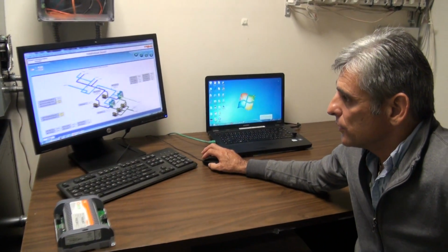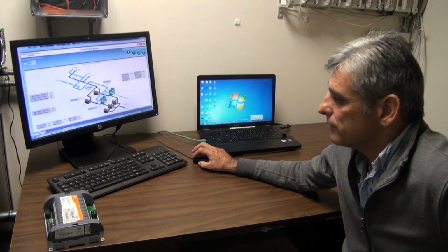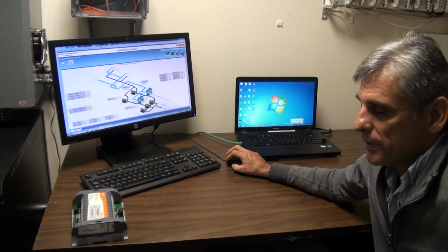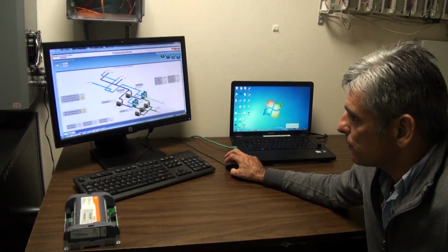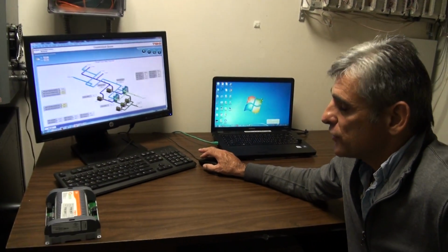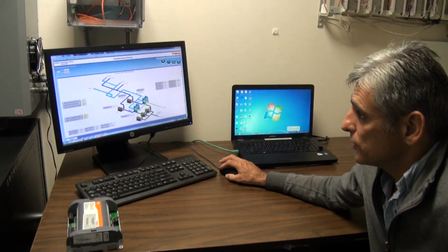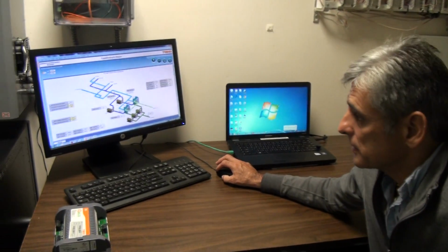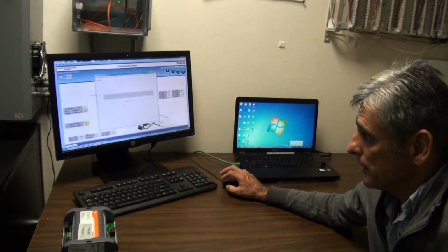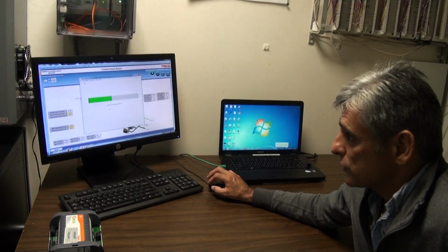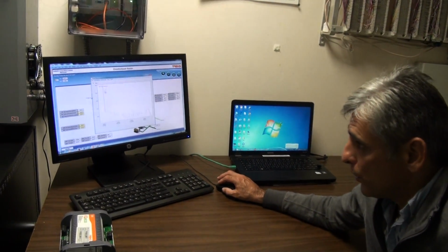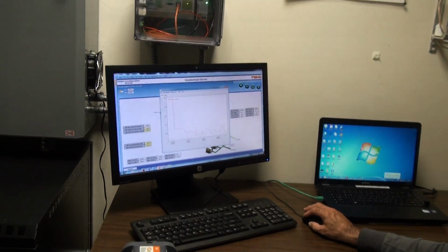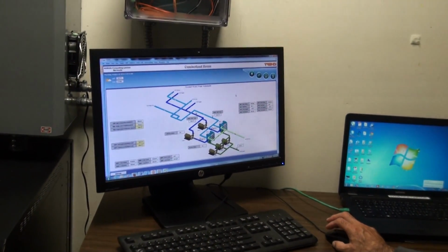And what we've done, through a BACnet IP, we've brought all the points for this plant into our Trend Control system and done a representation of graphics and trending. So we can trend, I think we've gone through this, we can trend every single point and show the client and the owner how the system's performing.